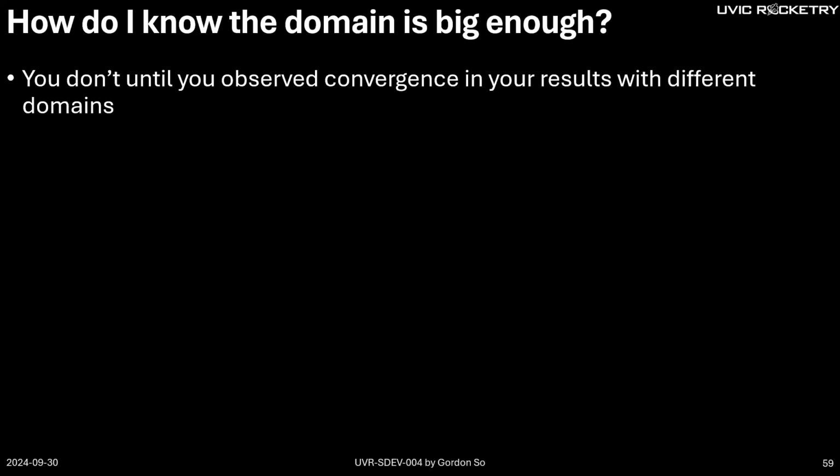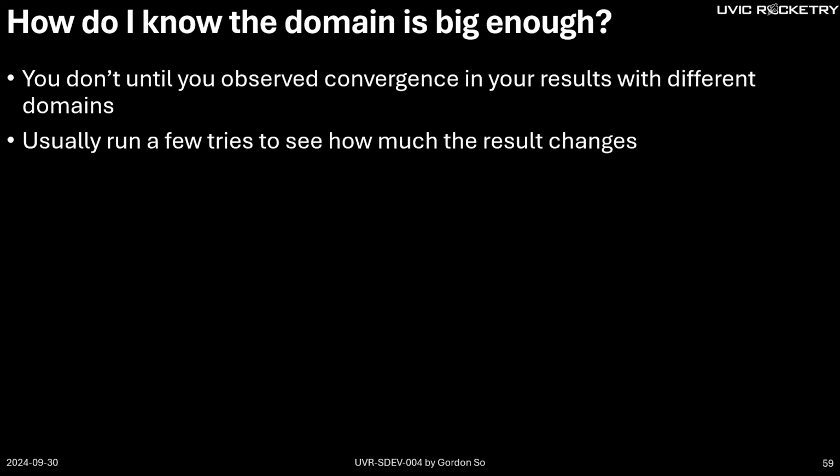So again, just rule of thumb to start. If you want to optimize your workflow, you can try to push it to a smaller domain. You need a few runs to see. So you don't need a fine mesh. We'll talk about refinement for the next section. But maybe sometimes you don't need as accurate a mesh to begin with to see if the domain is big enough.